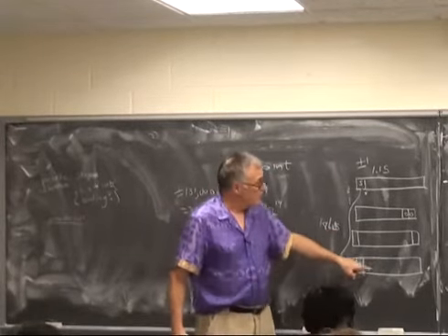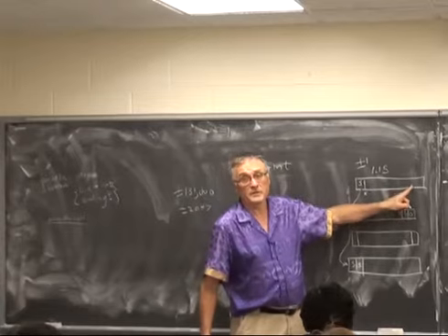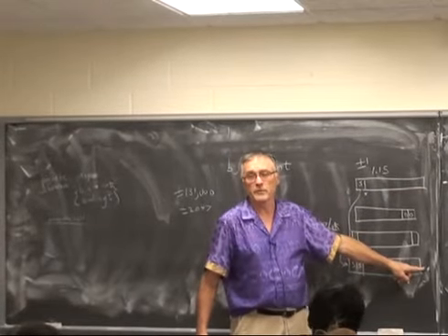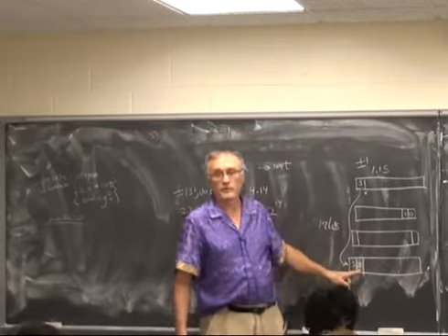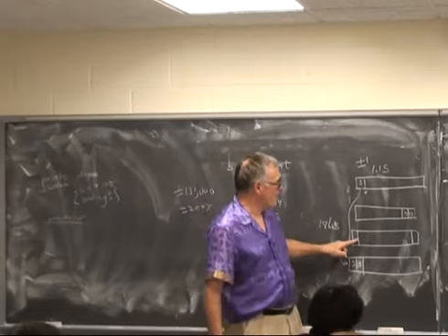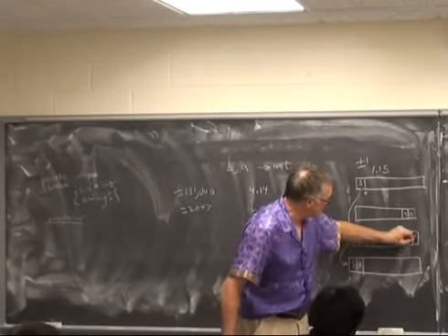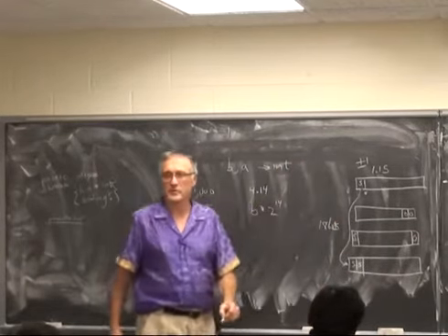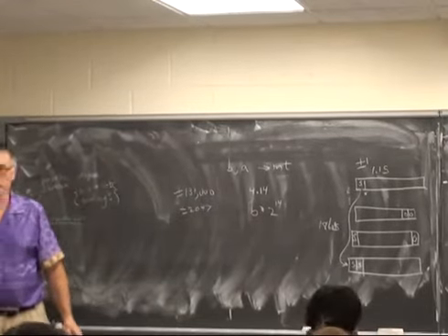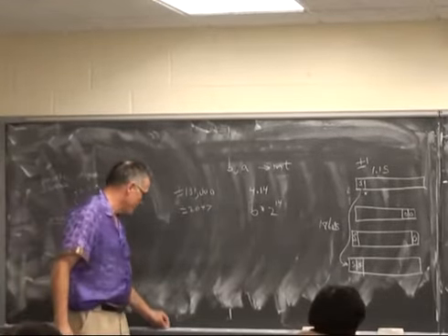Then you keep all the bits of precision of the input. You risk some round-off error during the arithmetic, but you have better overflow characteristics. If you put a sign bit here and a 0 here, you have some hybrid of the two. You can use anything you want, anything that works.